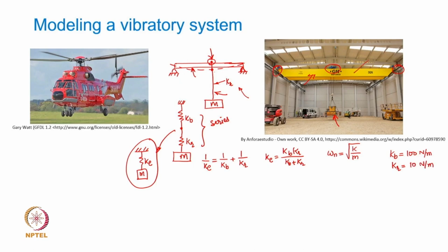For example, if the rope stiffness turns out to be just 10 Newton per meter, and in comparison the girder stiffness turns out to be 100 Newton per meter, and the mass being lifted, again not so realistic a value, but they are going to be relatively similar to the actual case. So, mass may be 500 kgs, and then the girder stiffness will be a couple of orders of magnitude more, but what is important is to let you understand how we simplify the modeling process.